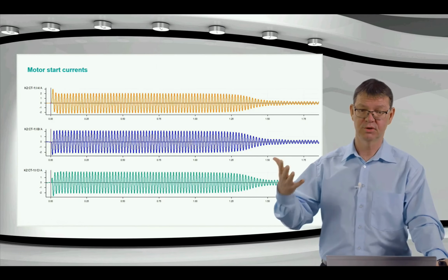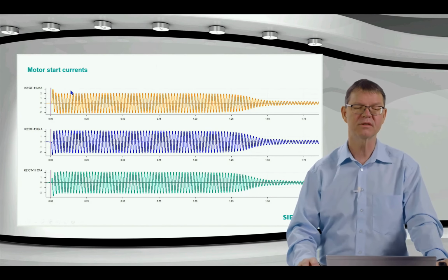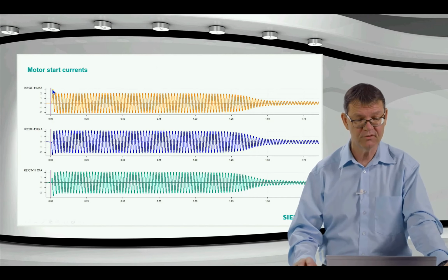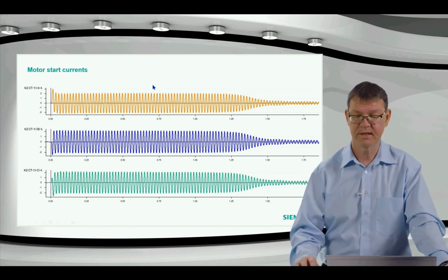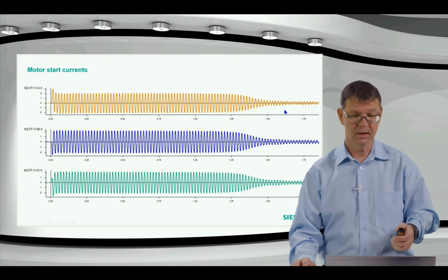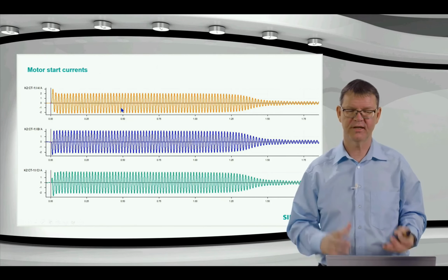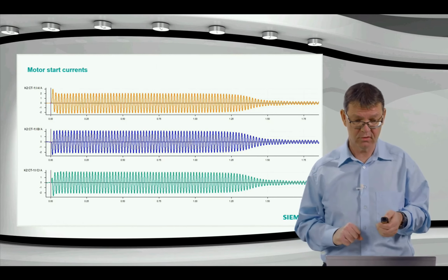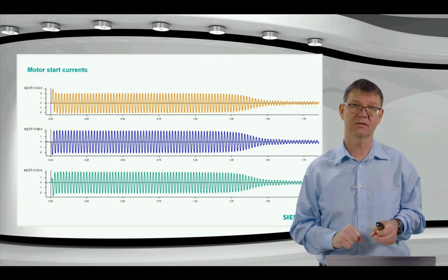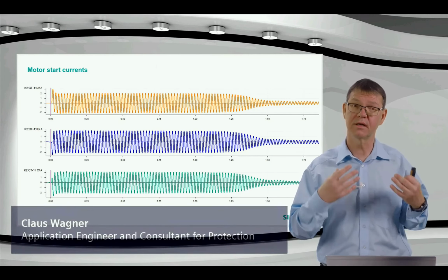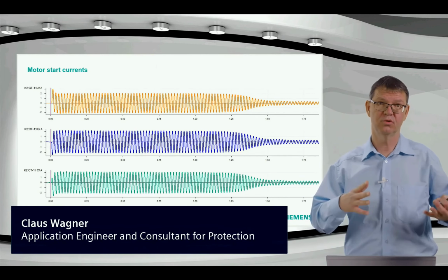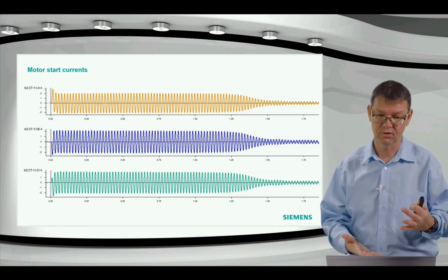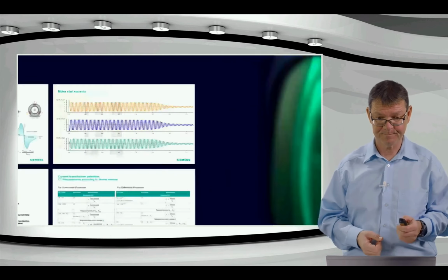The load on the motor defines how long the startup procedure is. The bigger the load, the longer the startup. But the amplitude of the starting current is more or less independent of the load. It depends on dimensioning factors of the motor, so how the motor was constructed. So we have to consider all these aspects because the motor is not just running, it's also starting up. For all cases, we need to be prepared with our protection function so that we don't have an overfunction on the one hand and are not too insensitive on the other hand.